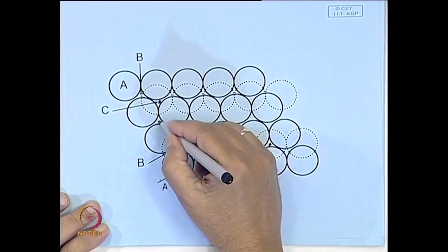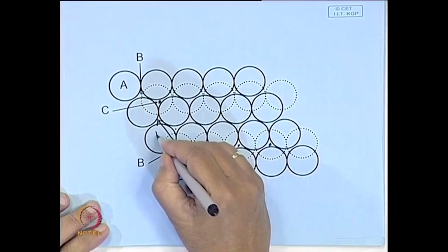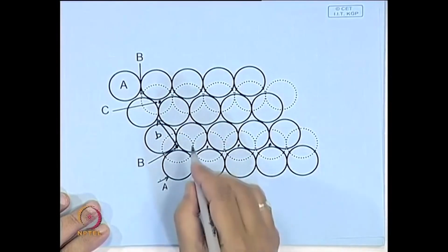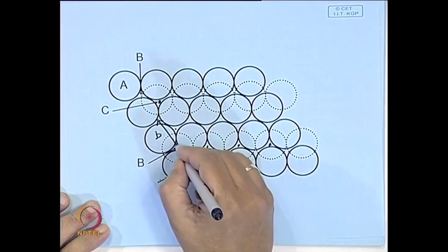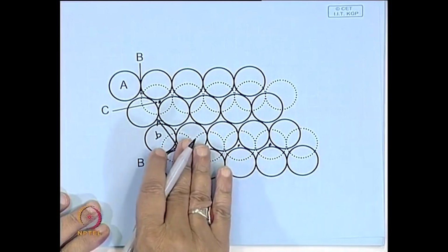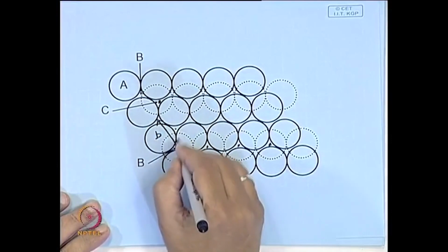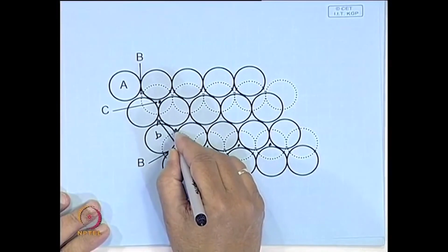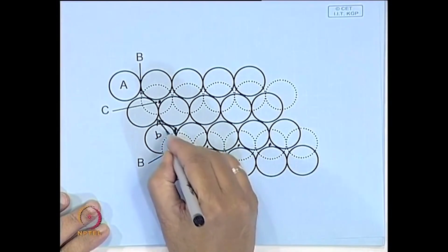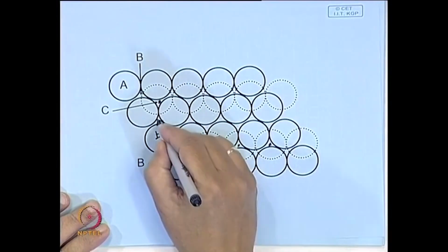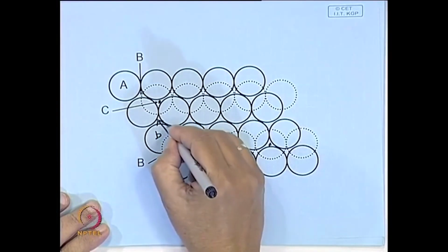So, basically this is the perfect dislocation Burgers vector. What is happening is, as if this atom has to go over the sphere, part of the sphere, whereas instead of going like that, if it moves through the valley, it is more energetically favorable. So, this perfect dislocation is split up into two partials, one like this, another from here to here like this,